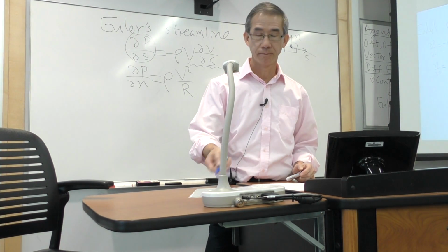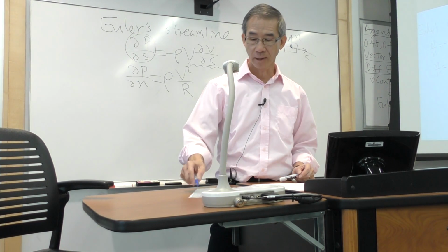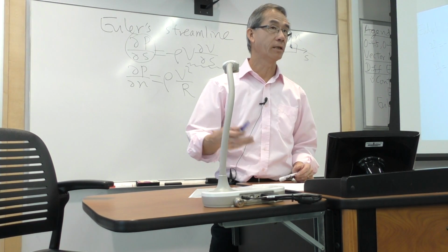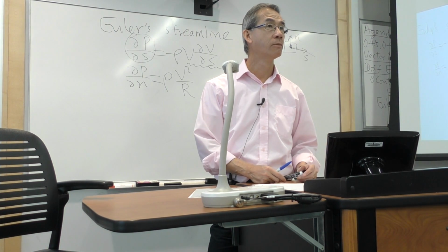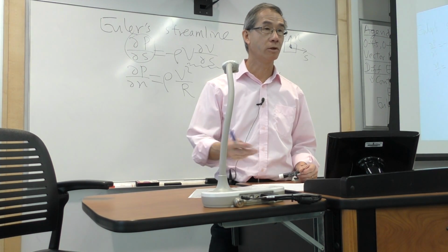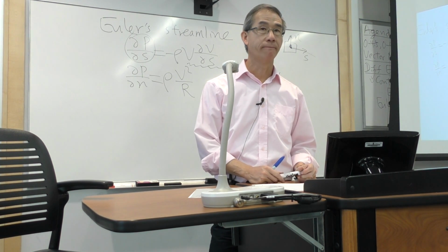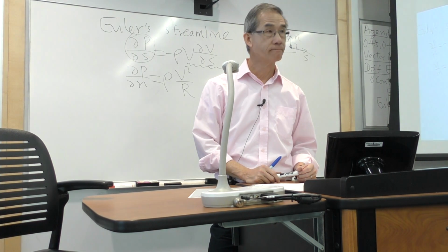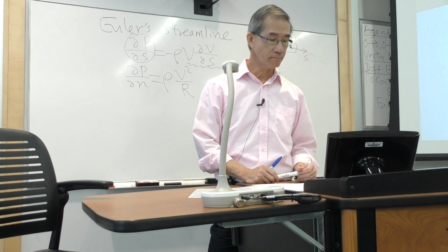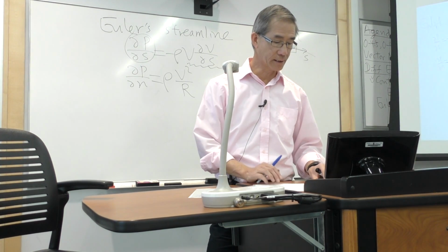So instead of mass flow, now you have momentum flow. You do the same on the right-hand side of theta plus d theta, and you continue just like we did on continuity. You do it in 2D, and then you extend it to 3D. Can you do that? You see how all this is heading, right? If you do that, you will be successful in proving the term on the right.